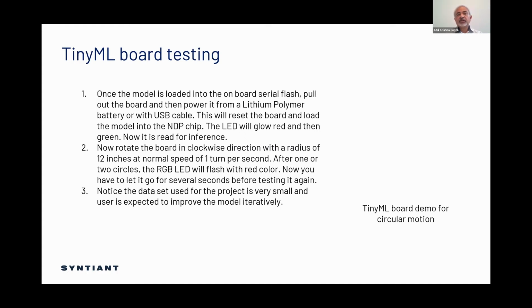Now, if you leave the USB cable connected to it, you might find that your movement is somewhat restricted. And that's one of the key things when you are working with sensors: when you're capturing the data and when you're testing it, the conditions have to mimic the real product. If you have the wire hanging, it might restrict your movement, and it may not capture the data the way you intend.